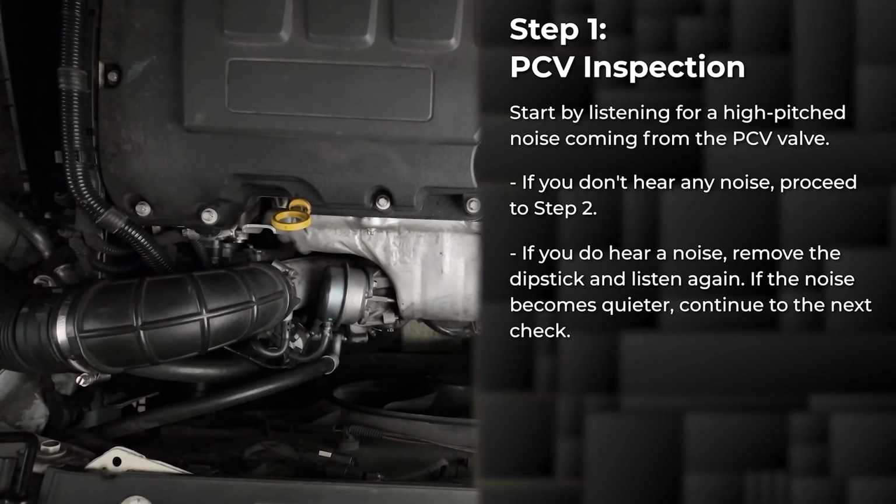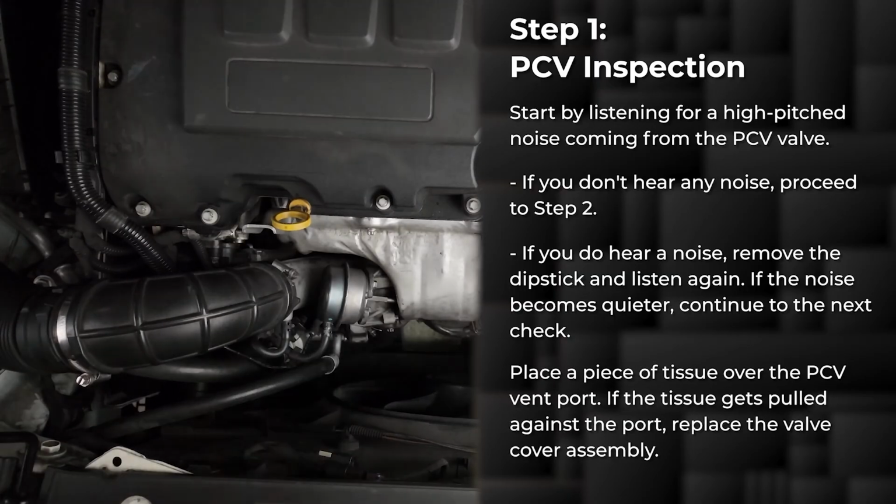If you do hear a noise, remove the dipstick and listen again. If the noise becomes quieter, continue to the next check. Place a piece of tissue over the PCV vent port. If the tissue gets pulled against the port, replace the valve cover assembly.